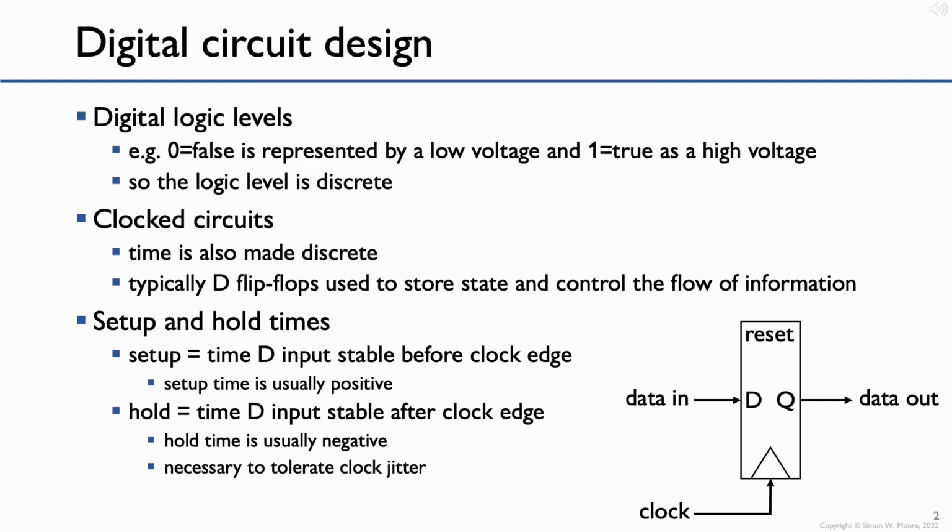Setup and hold times are absolutely critical to such a device. The setup time is the time the D input must be stable before the clock edge occurs, and that setup time is usually a positive value. In other words, the D input has got to be stable before the clock edge, and if the data and the clock change at the same time, then the flip-flop basically becomes unreliable. It goes metastable.